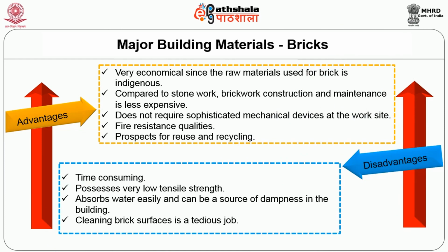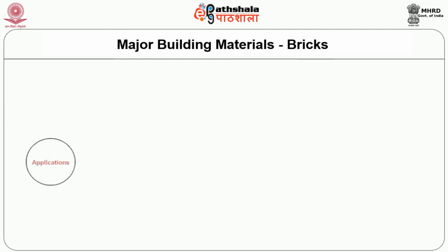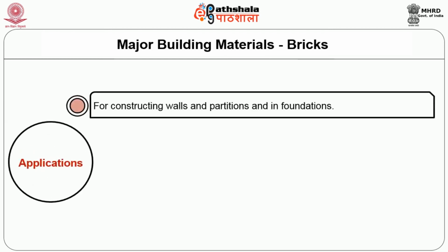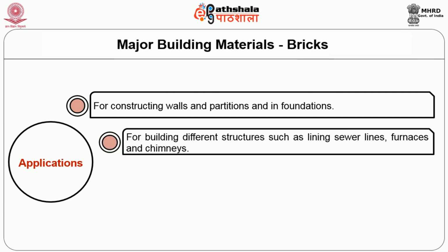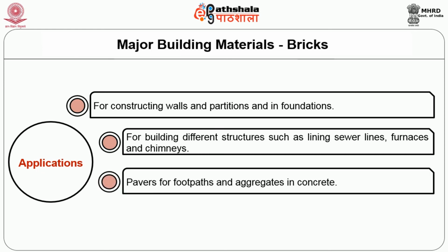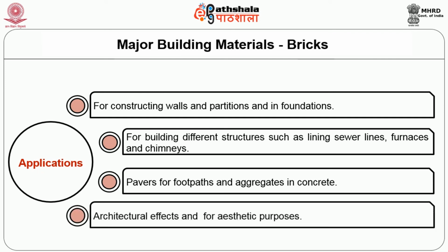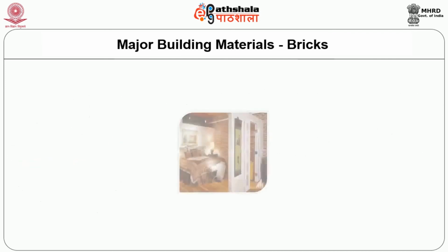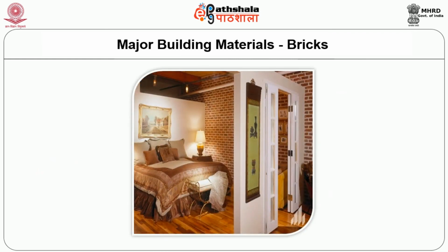The disadvantages are they are time consuming, they possess very low tensile strength, absorb water easily and can be a source of dampness in the building, and cleaning the brick surfaces is a tedious job. Applications: for constructing the walls and partitions and foundations, for building different structures such as lining sewer lines, furnaces and chimneys, as pavers for footpaths and aggregates in concrete, and for architectural effects and aesthetic purposes. The image shows bricks used as a decorative wall in a bedroom.